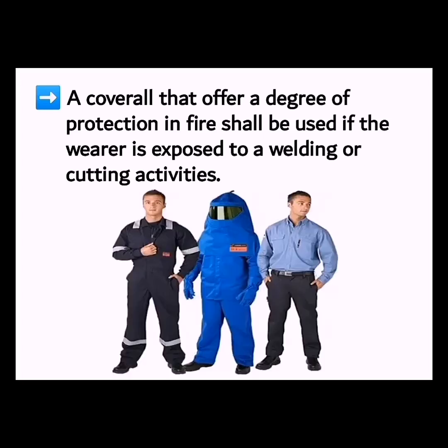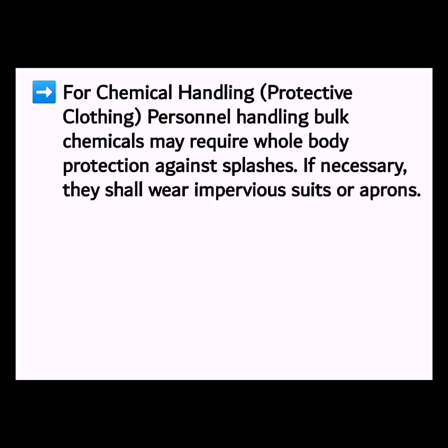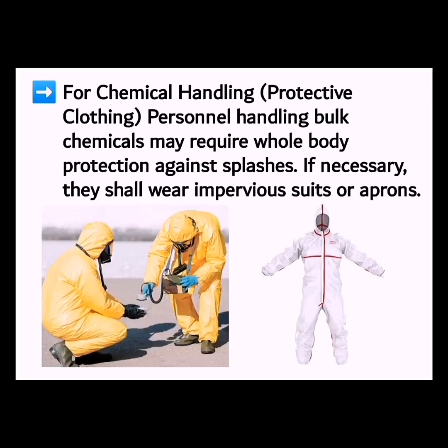Body protection. Coveralls that offer a degree of protection in fire shall be used if the wearer is exposed to welding or cutting activities. For chemical handling, personnel handling bulk chemicals may require whole body protective clothing against splashing. If necessary, they shall wear impervious suits or aprons.